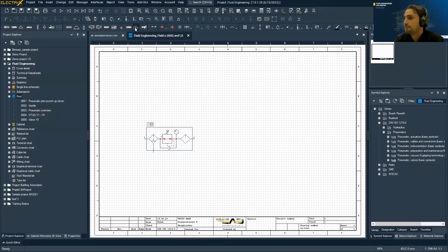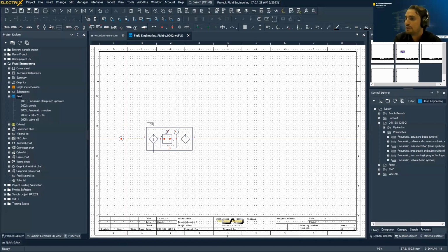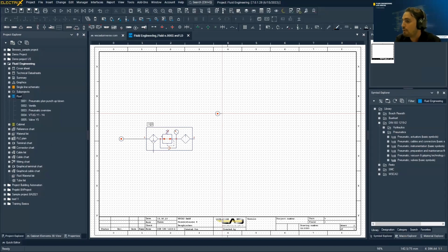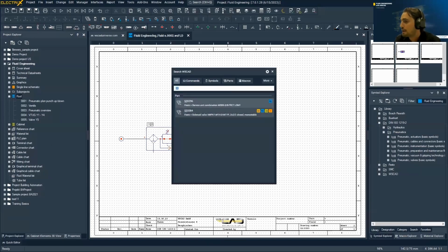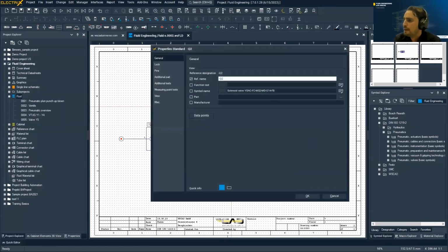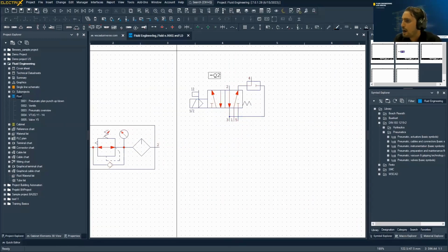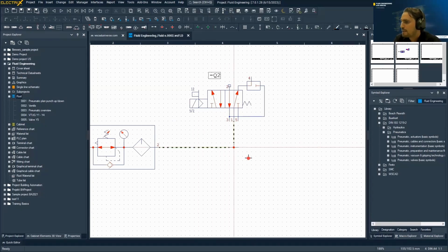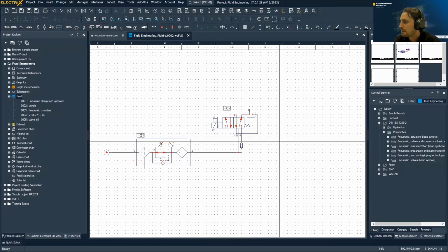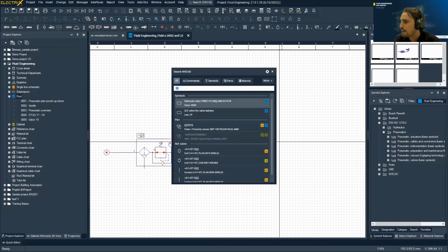And for more efficient design, we can use our toolbar, which we just designed before. And for our case, we will also need, again from this quick search, a solenoid valve, like this. And now we have this pneumatic T-top. We can easily connect these elements like this. And maybe we will need a muffler too. Here, you can see it's very easy and very fast. We can easily and quickly create something.